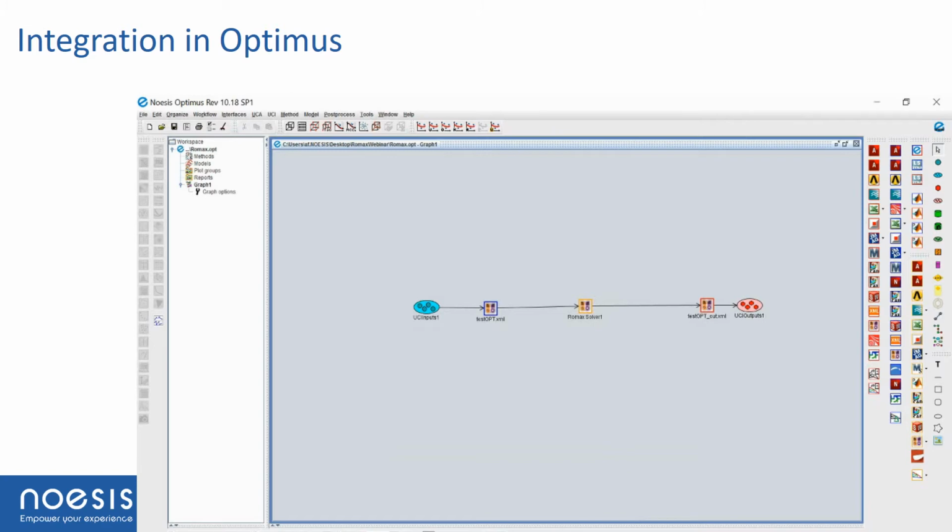But if you don't open and close Romax every time, it means that you cannot use the parallel mode. If you have different machines to run, you can, for example, submit different Romax computations if you have multiple Romax licenses available. For example, during the weekend or at night, you'll be able to take advantage of those extra licenses, especially if the Romax runs are getting longer.